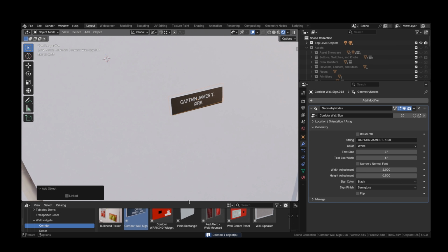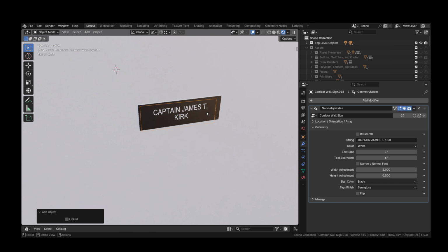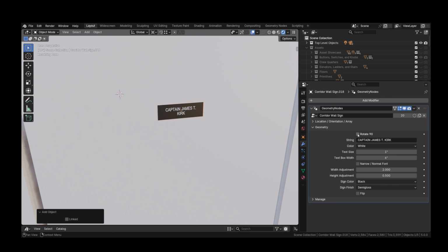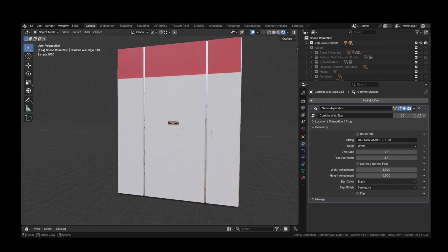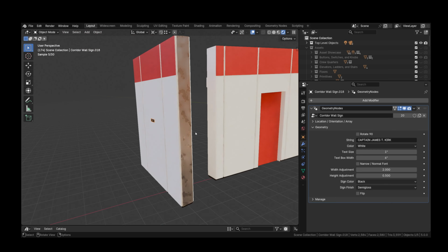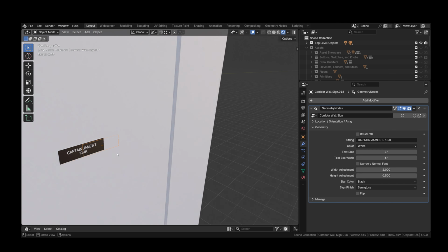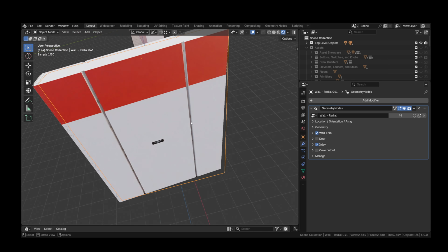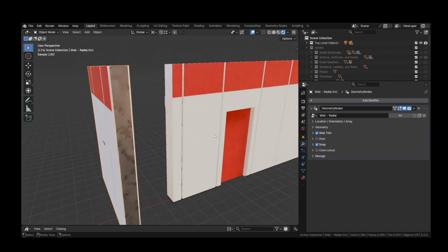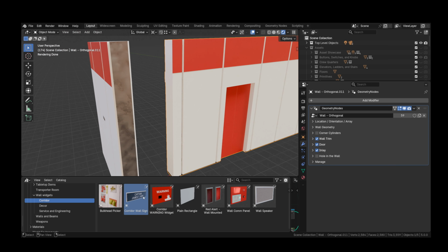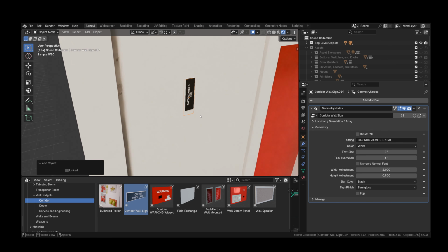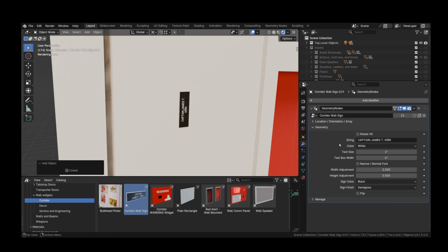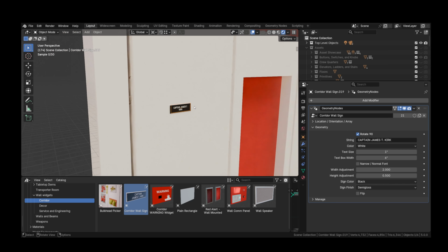You have corridor signs. Should be pretty simple to use. These assets I have with this rotate 90 checkbox here, which is a necessary evil right now. I wish I didn't need that. But as we bring those assets into a wall, if we're putting them on a radial wall, they come in the proper orientation. If I put that same asset onto an orthogonal wall, it comes in 90 degrees out of whack. So I've got this rotate 90 just to have a quick manual intervention there to straighten that out.